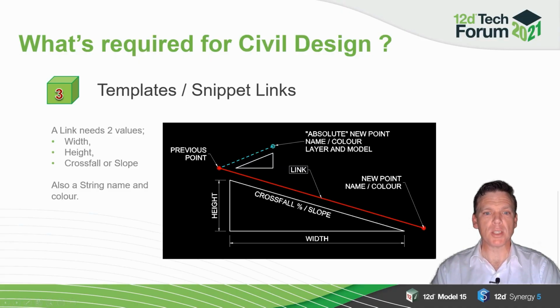Also, we are able to insert links absolutely. So they don't always actually have to go on the design surface. We can actually insert links absolutely above or below that surface. And these tools are often used to create the subgrade surface and services design, utility services design underneath the design surface also. So we're not just set at one surface itself, we can actually do multiple layers within the design process if we want. So we'll touch on some of that also.